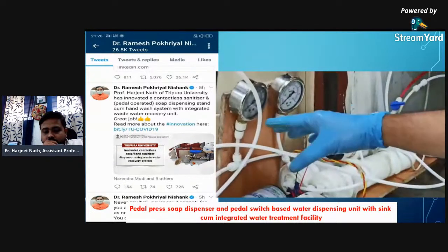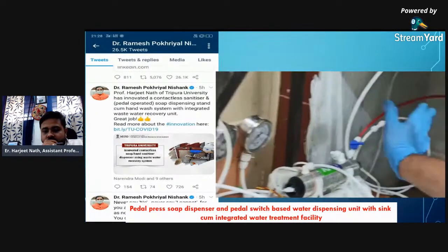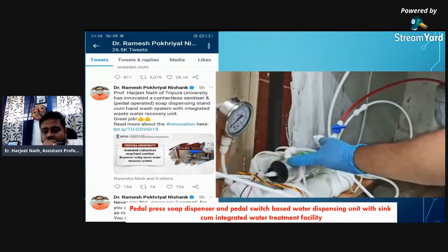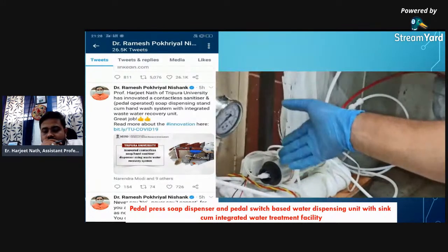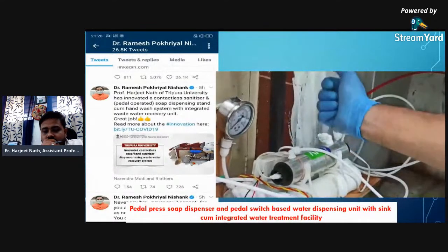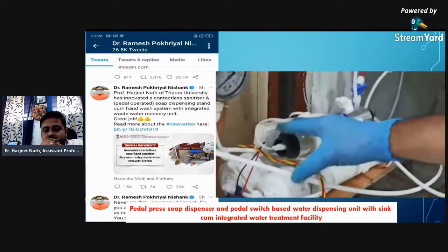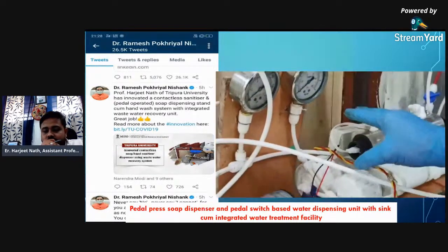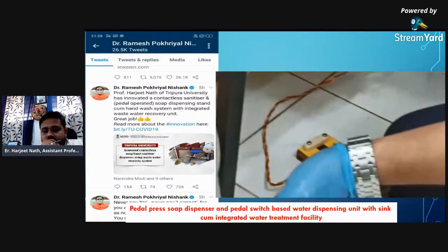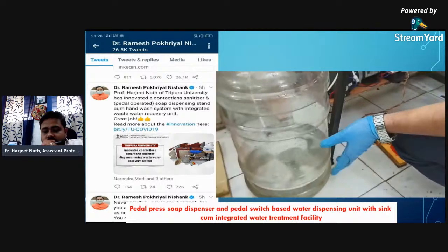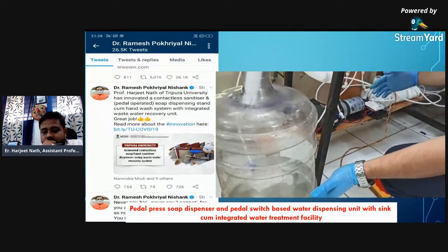And then what happens is that the water gets treated in setup 1 and 2, and from 1 and 2, the wastewater goes out as a reject, and the clean water comes to the UV system, so that if any microorganisms present get treated here. Basically, when you have a very good membrane-based system, there are more chances that the microorganisms will not be coming up. Anyway, when you have the soap solution here, the microorganisms get ruptured, and anyway they are already in a killed and ruptured form here. But even if some microorganisms are